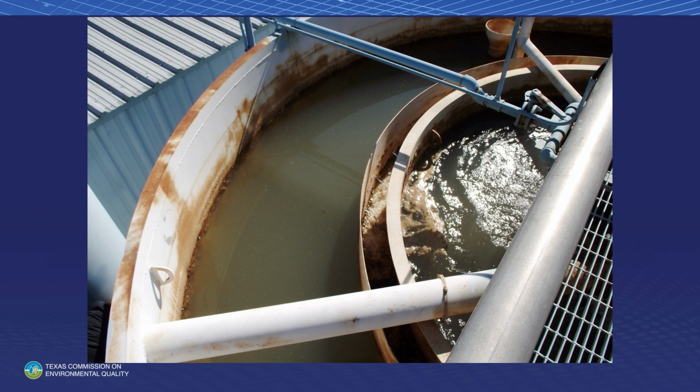They looked at it and saw that they were having a little problem with short circuiting, so they went in here and built a sleeve around that port to try to force the water that came through here back down so that they could get more sedimentation time inside that said basin. It didn't work too well, let me put it that way, okay? Again, we had some real issues with this particular sedimentation basin.